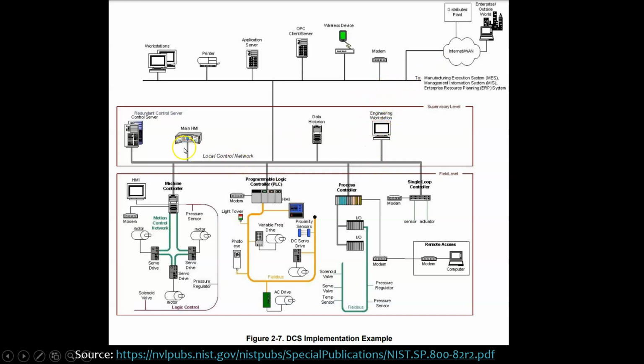But actually these guys, like the engineering workstation, the data historian or the HMI, are speaking a different language, different protocols, industrial control protocols like Modbus and DNP3. There are specific industrial protocols that IT cannot actually speak. So there is no direct communication between the enterprise and the OT or the ICS world.